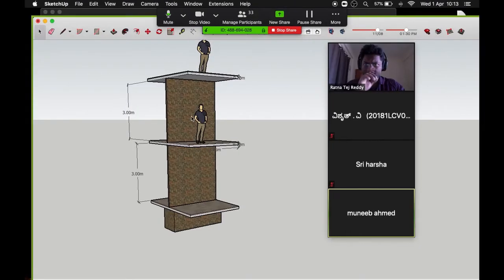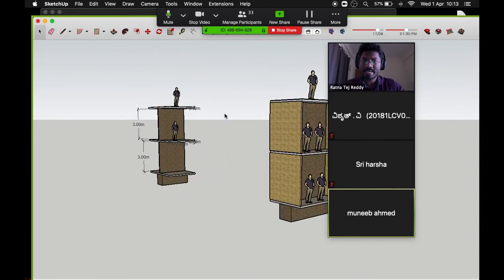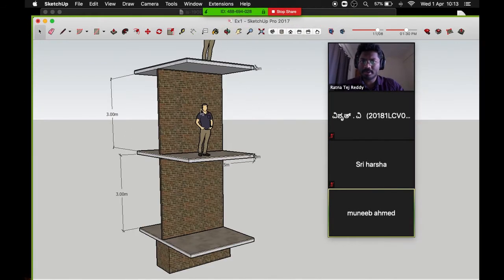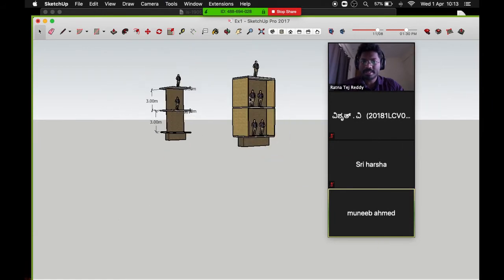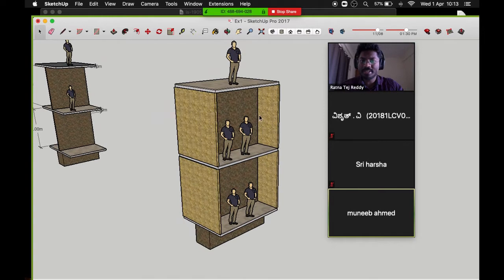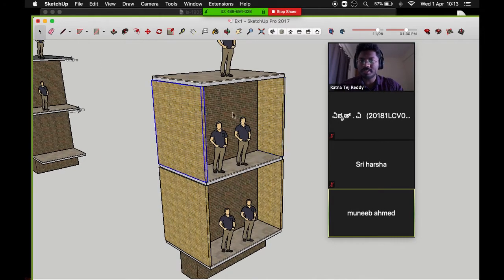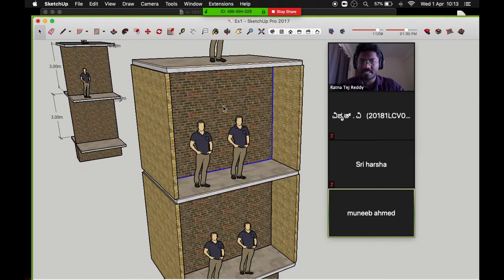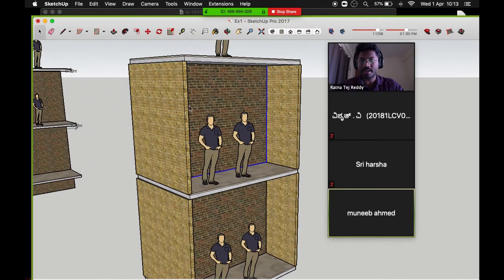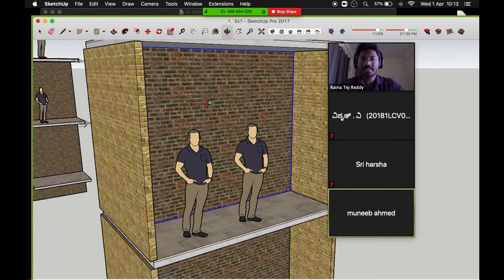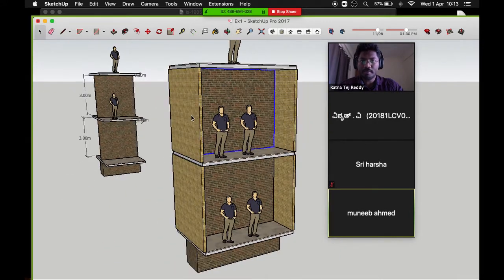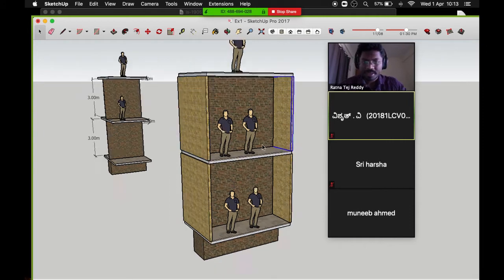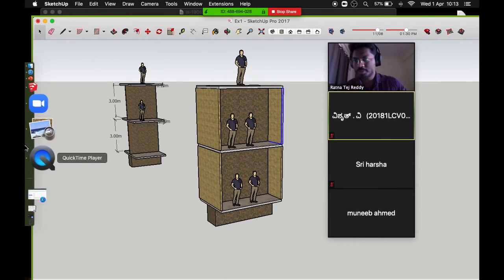Yeah, in the previous problem, we have seen that there are no lateral supports or lateral end conditions in example 1. But in this example, you have end conditions, which are two cross walls on either side of the wall which we have to design. If you can see, I have shaded differently for the two types of walls. This is the wall that is stiffened with the help of the cross walls on either side of the main wall. Now, let's walk through the design procedure first.